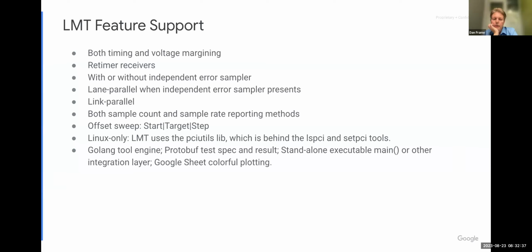One of the questions I had was about your voltage margining. I actually did not know that was capable. I knew of the timing exposure, but I didn't know that the voltage was. Is that like the DC offset margining, or is that amplitude margining? It's the amplitude. It's the eye diagram, the vertical axis, the height of the eye. Okay, got it. Thank you. Yeah, that's optional in PCIe 4, but required on PCIe 5.